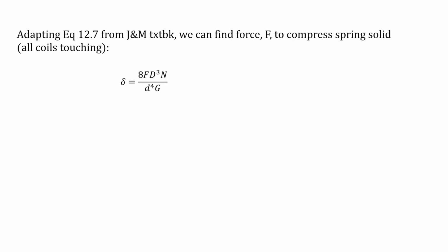So in order for us to find out whether the spring is actually going to return to its original length, we first need to find the force required to actually compress that spring totally so that all those coils are touching. And then from there we can find the shear stress using that force. So we have our equation 12.7, from your textbook, that we can rearrange to actually solve for the force, where we have this equation here.